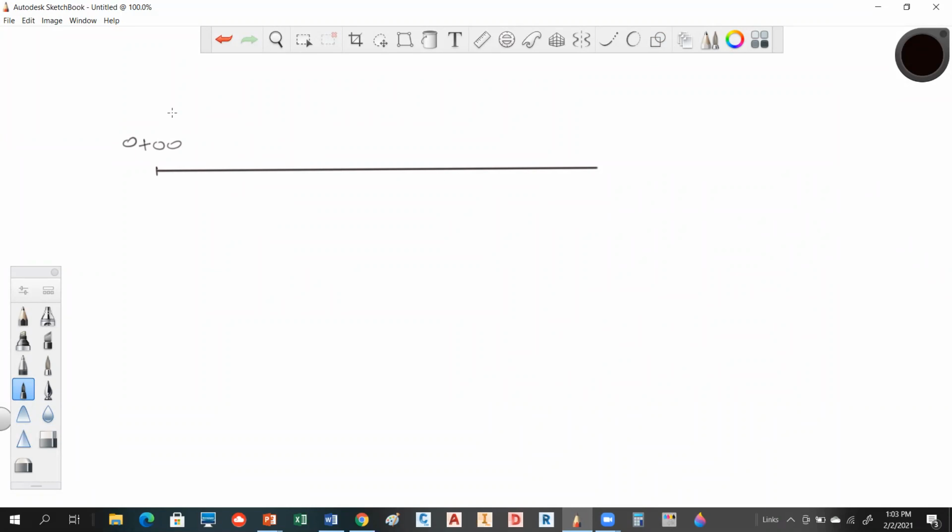So let's talk about a station along an alignment. So what is an alignment? Anybody know? Well, it's kind of like a number line, okay? And that number line has a 0 starting point. And all we do is measure distance along this number line. So if we measure out 100 feet, we call this 1 plus 00. If we go another 100 feet, this is 2 plus 00. Get the idea? 3 plus 00. Okay, so this would be called my alignment, and this is my stationing along it. Everybody okay with that?